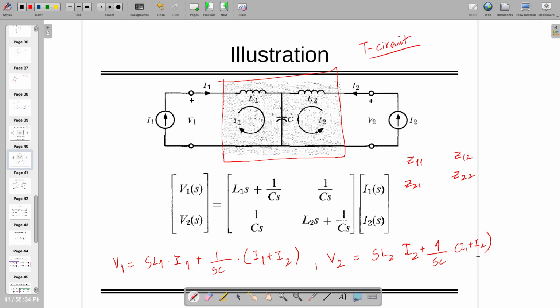And then you can write down this matrix. This matrix is two port. You will always have a 2 cross 2 matrix. You will not have more than 2 cross 2 in the case of a 2 port network. But if you are writing, let's say, an impedance matrix using the technique which we have learned earlier, and there are three loops of current, then it will be a 3 cross 3 matrix, or higher than that.